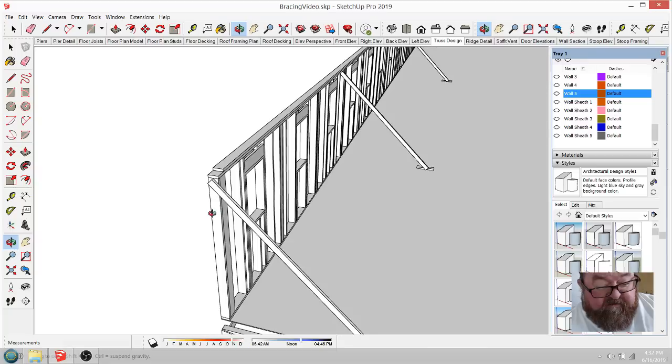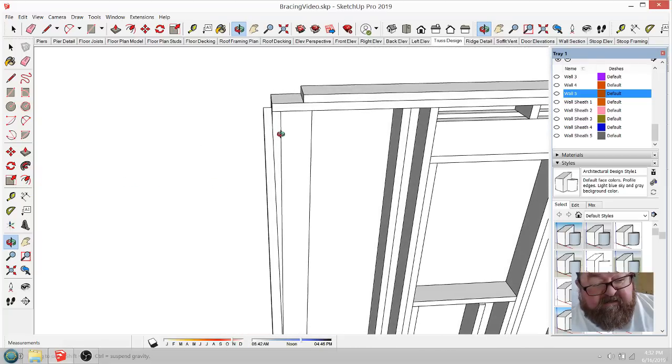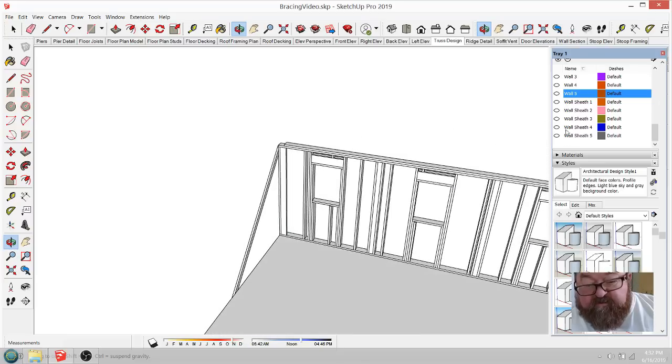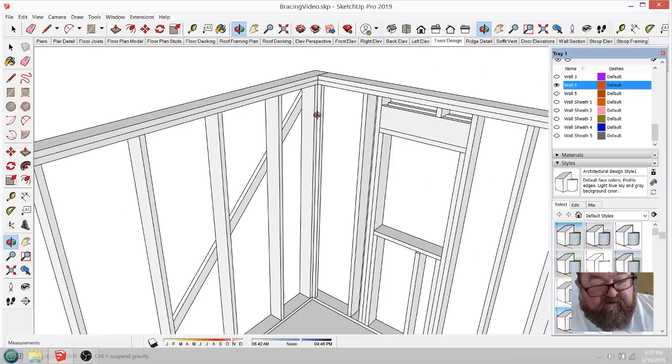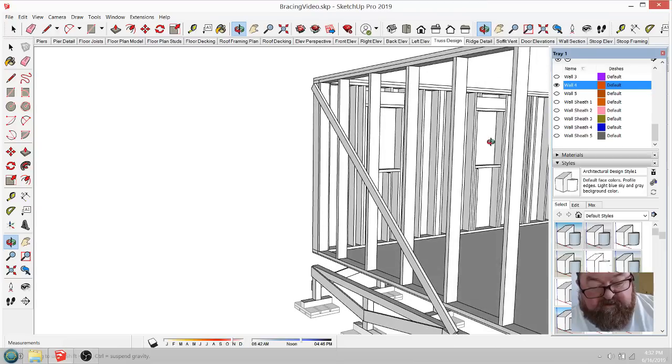These corner braces are nailed up on the outside of the corner, so that wall number 3, wall number 4, can be built without removing that brace. You see? So that brace, where's my floor framing?